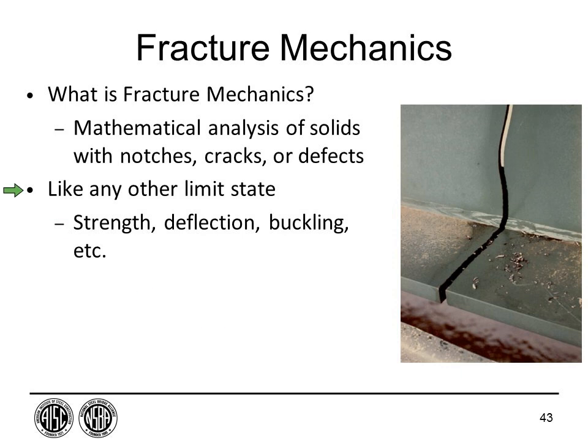The term fracture mechanics, the branch of study called fracture mechanics, is something you may have heard of. And what is it? It's one that a lot of times we get scared of for certain reasons, but really it's just a way to consider the effect of cracks or defects or notches in a solid. Think of it like any other limit state. So you already do strength calculations or deflection checks or buckling calculations. That's to check strength for some load combination and some failure mode. Well, fracture mechanics is looking at how much of a crack the material can tolerate.